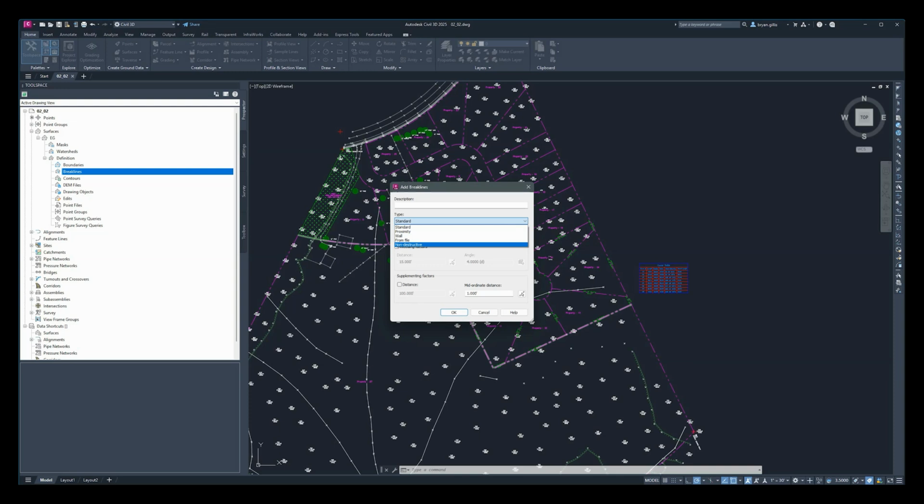It's going to utilize the X, Y, and Z coordinates of proximity break line vertices and determine those from the surface's 10 points that are within the closest proximity to the corresponding vertex of the break line. Our wall types are going to be defined using grading feature lines, 3D lines, 3D polylines, splines, or by specifying points. The wall break line is going to be stored as a standard break line, but defined differently in that you're going to have to provide offset sides for the entire break line, as well as elevation differences for each vertex for the entire break line.